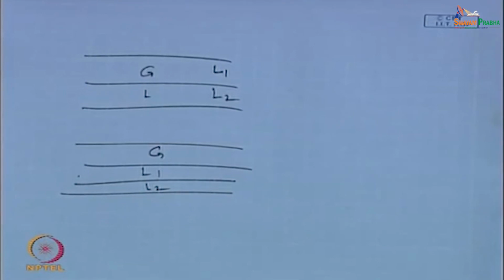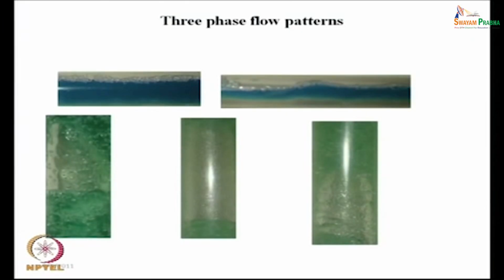But we find that whenever we increase the gas flow rate by a very small amount also, there is a tendency of slugging and slug flows occur. The slug flow will be evident, the photographs are not very good I believe. From here you can see these are the Taylor bubbles, and this is the liquid slug. Here the liquid slug portion is shown much more evidently.